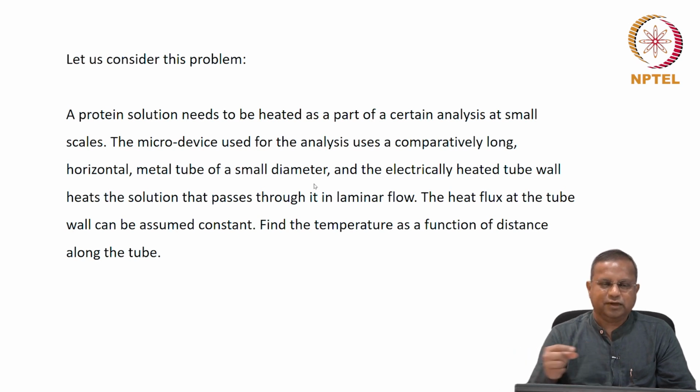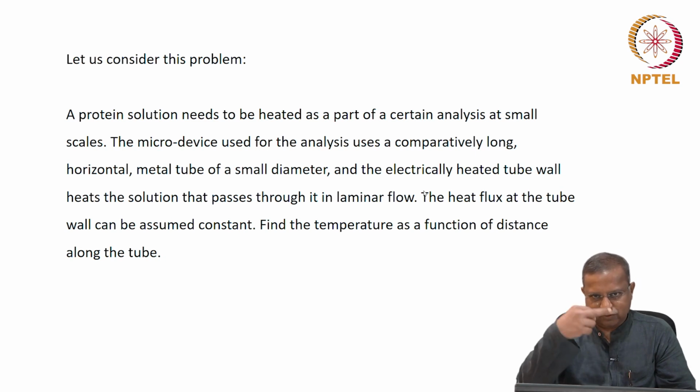We have already seen that rho v d by mu, for a given rho, given d, given mu and the given solution, given liquid, since the d is very small and the usual conditions are that v is also small, then you have laminar flow conditions there. They are going to flow in cylindrical layers.